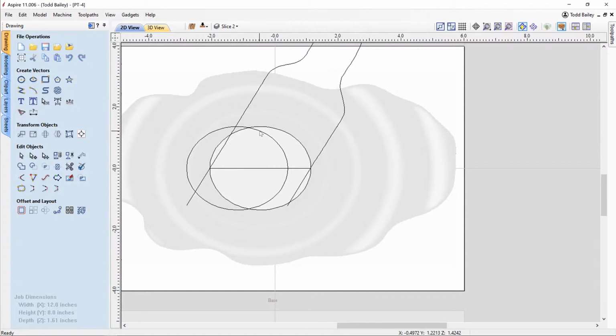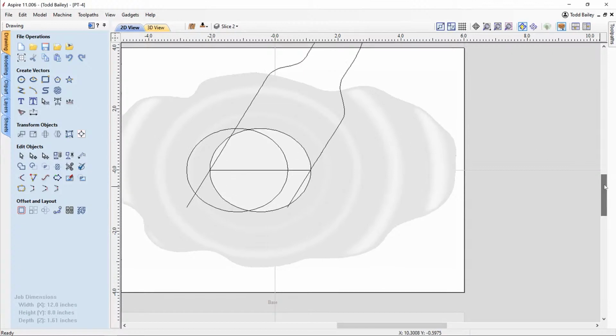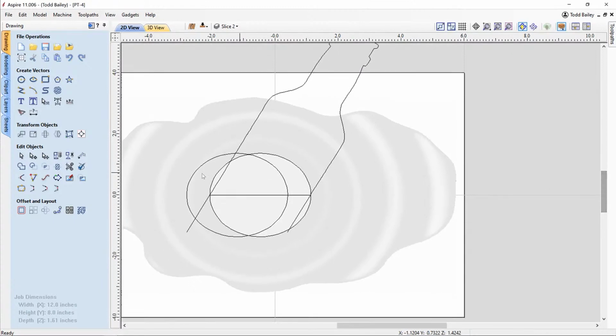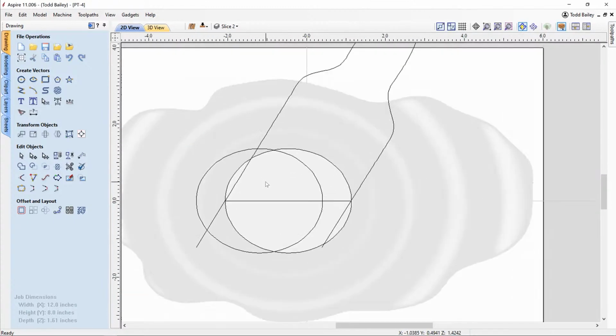And then we have enough vectors here, believe it or not, to create a 3D shape that we can subtract out and then level clip to only keep the bit that we want to create this interesting kind of hole that typically you can't do on a CNC machine because we need to have an undercut and we can't do that on a 3 or 4 axis CNC easily.